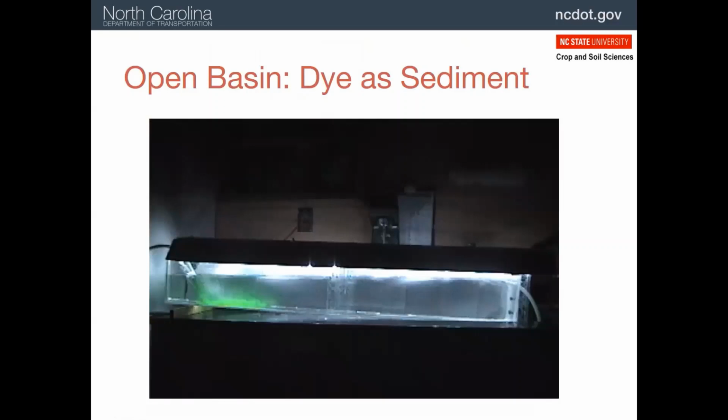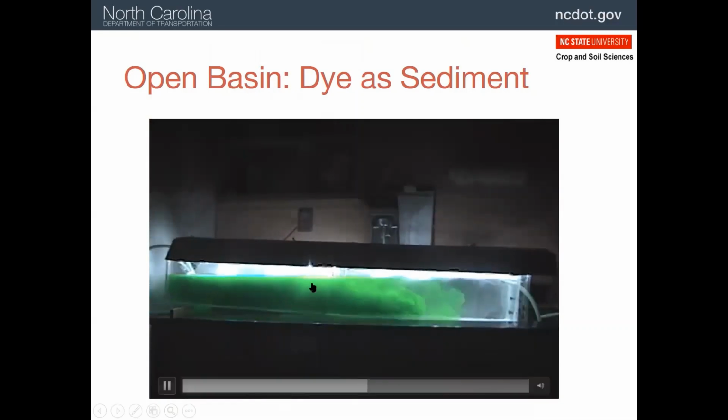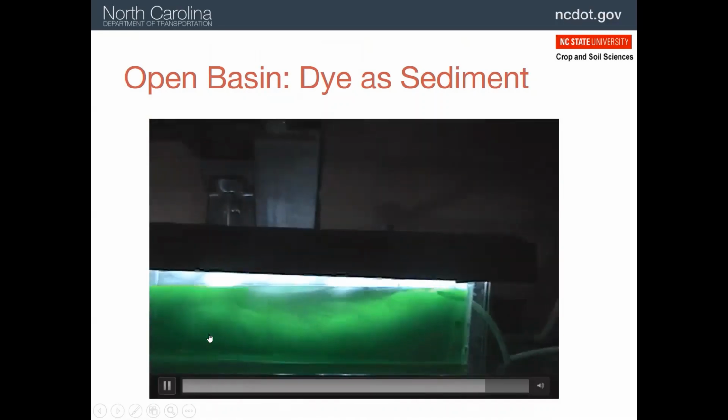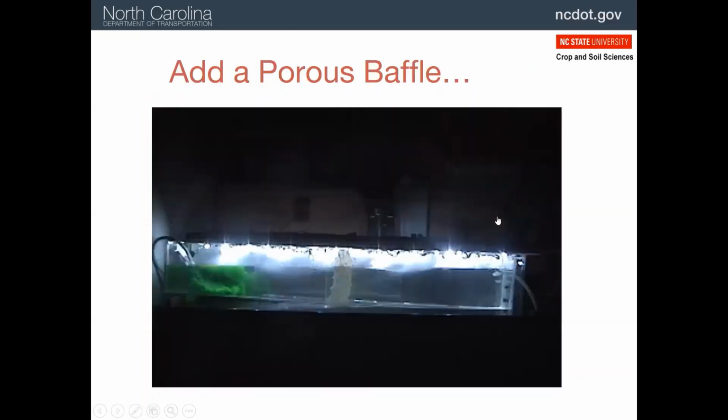To show how porous baffles work, let's look at a laboratory demonstration of an open basin. And the dye you see here is sort of representing your turbid, muddy water. So picture that. And here we go. You can see the flow coming in, a lot of turbulence. I've sped it up so you can see the whole basin has a lot of turbulence. So that's important to think about when we go to the next slide, and we look at what happens when you put a single baffle into that basin.